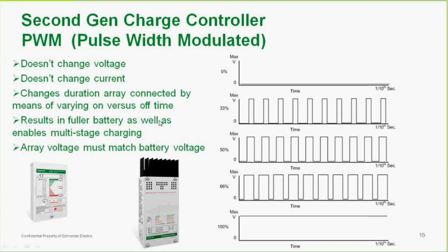So, for an example, if we're trying to maintain a target voltage of 14.4, and we'll just say that we have 2,000 watts of solar coming into the batteries, and the batteries are full. We have 2,000 watts of solar coming in and no loads. The switch would just be off because we would need no more solar to maintain battery voltage. But what if we increased the load up to match? So we increase the load now to 2,000 watts. Now we'd be going down to this scenario. The switch would be on constantly.